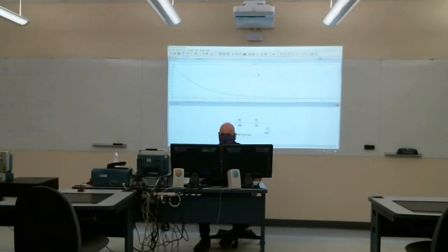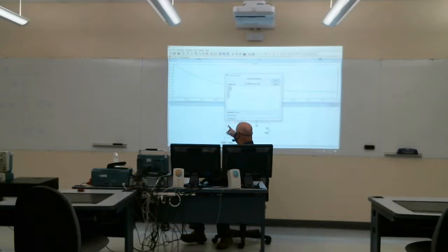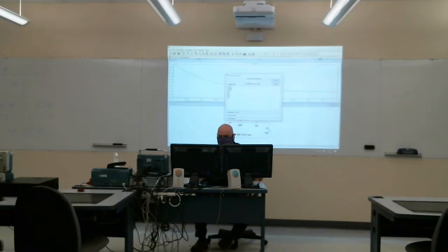What I usually like to do, and what you can do pretty easily, is add to the graph your theoretical expression. And our theoretical expression is 50 times exp of minus 6 times time. Again, every different software you work with uses different variables. In LTSpice, it's time to represent time. So this is our theoretical expression.